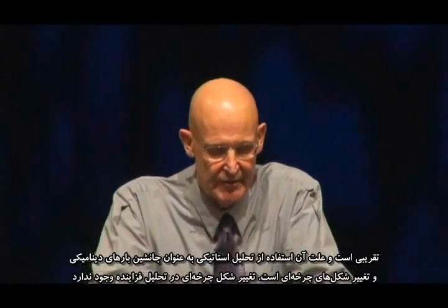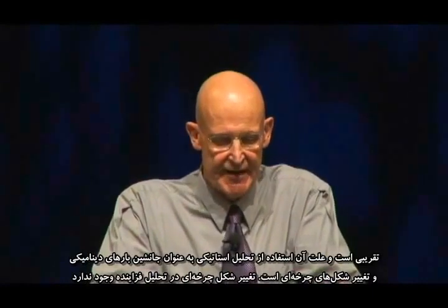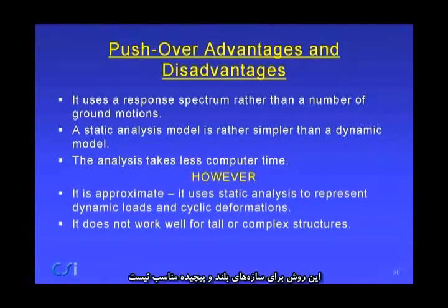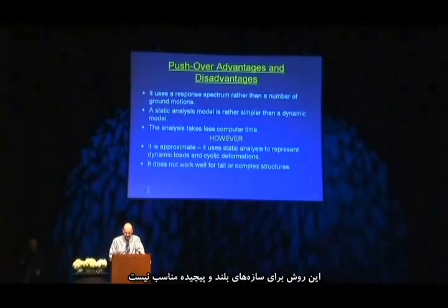Firstly, it is approximate, and the reason is it uses static analysis to represent dynamic loads and cyclic deformations. There's no cyclic deformation in a pushover analysis. And it does not work well for tall structures, and it doesn't work well for complex structures.